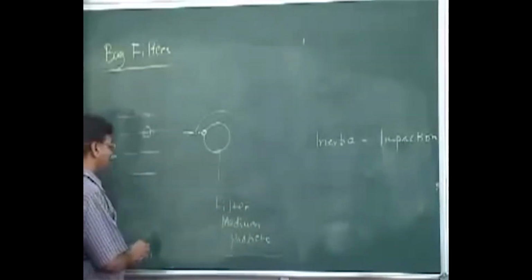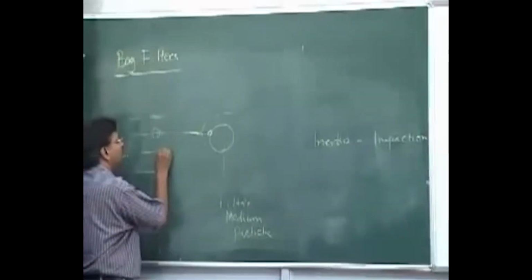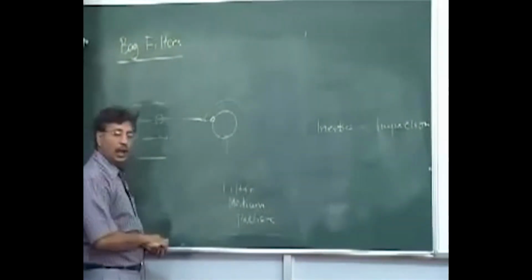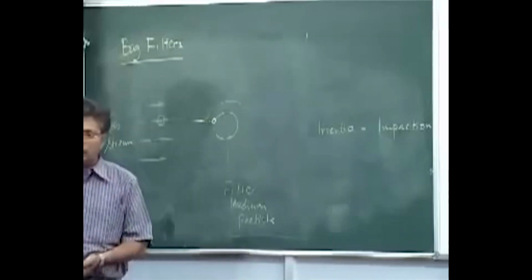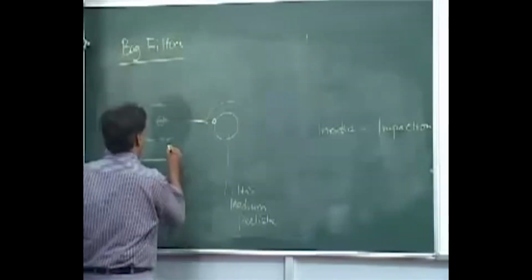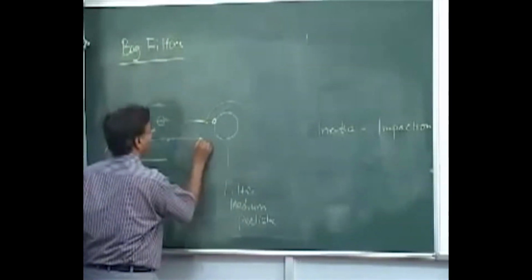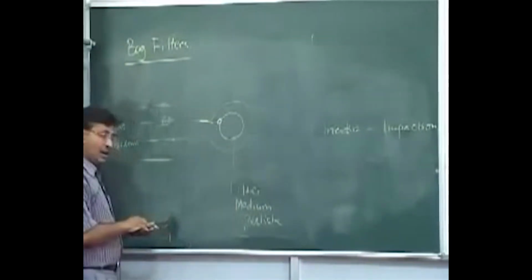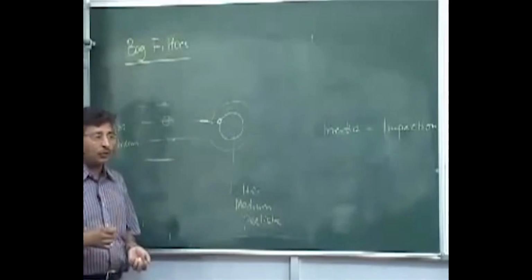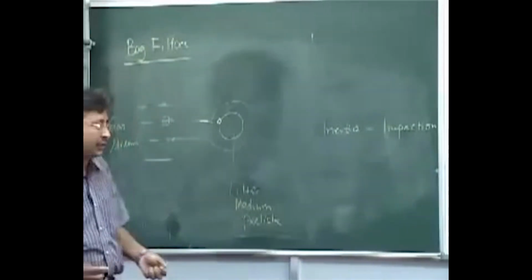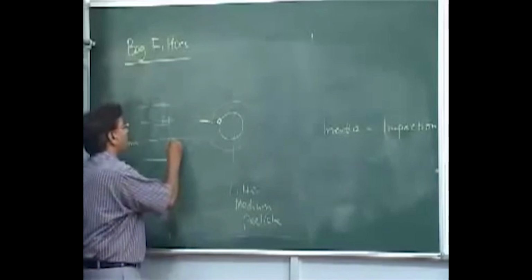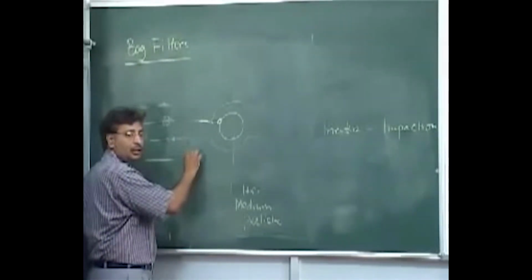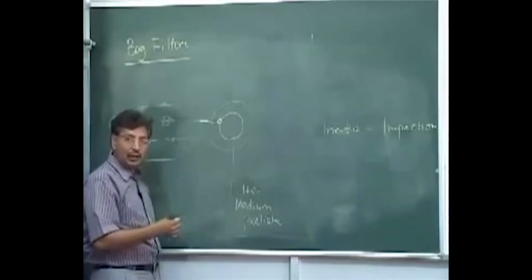Second thing is, let us say a particle is very small, a very small particle. It will hardly have any inertia. So the gas stream will go like this. This particle being very small, sub-micron size, 0.1 or something like this, will have some kind of motion. What motion is that? Brownian motion. Very small particles will have Brownian motion.